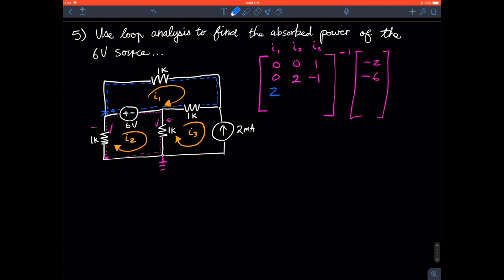Then we see what it's touching in terms of window panes, and we say that's a negative. This guy right here is touching I3, so I3 is just going to be -1. Literally all we did is count. We didn't even write a single equation. The other thing is we were walking clockwise, so we walked through this. This is a -6 if we were to write out an equation, but when we go to the other side, we flip the sign and it becomes a +6. We got +6 right over there.